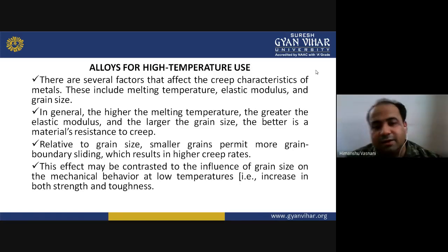In general, the higher the melting temperature, the greater the elastic modulus, and the larger the grain size, the better is the material's resistance to creep.